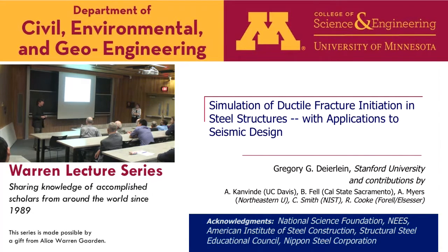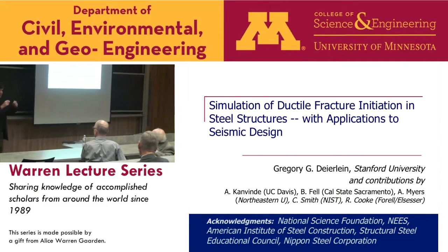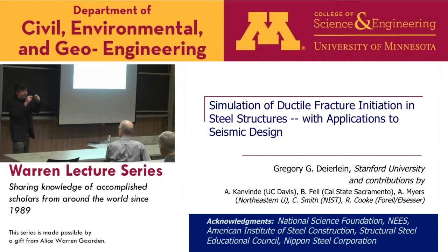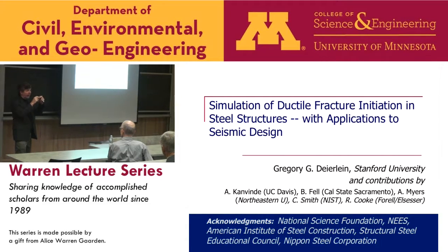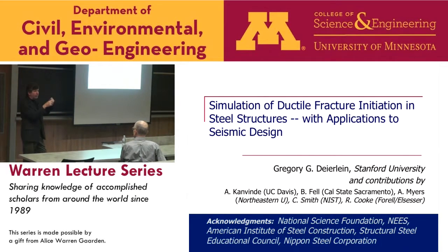So first, how we characterize the material, like in the heat affected zone, we put those notch bars through the area we thought to be the heat affected zone. And then we tested those and analyzed those and backed out a fracture index. So we got a distribution of that critical fracture index and the dispersion on that. Then we would take that as given, and the demand we were calculating was in a fairly deterministic fashion.